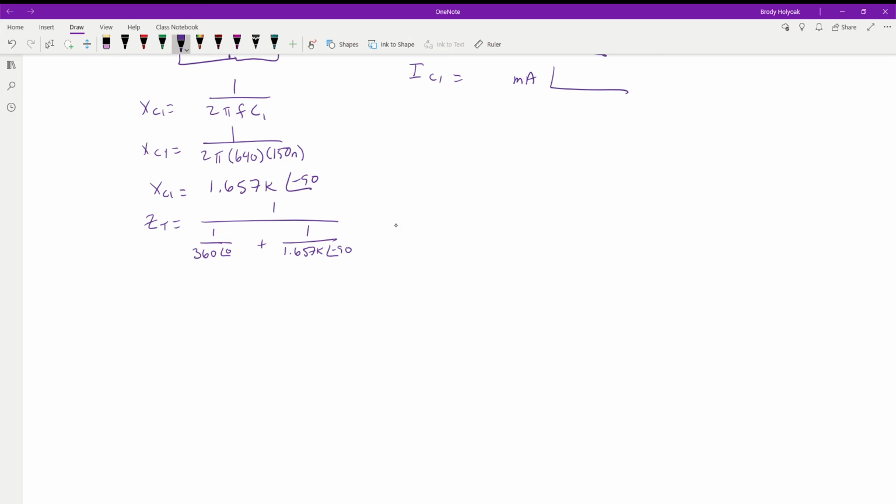So our impedance turns into the admittance, and that leaves us with this, which doesn't look quite as scary, and it's easier to solve. Now we're going to find the conductance and the susceptance, and those are going to add together so we find the admittance of the entire circuit.